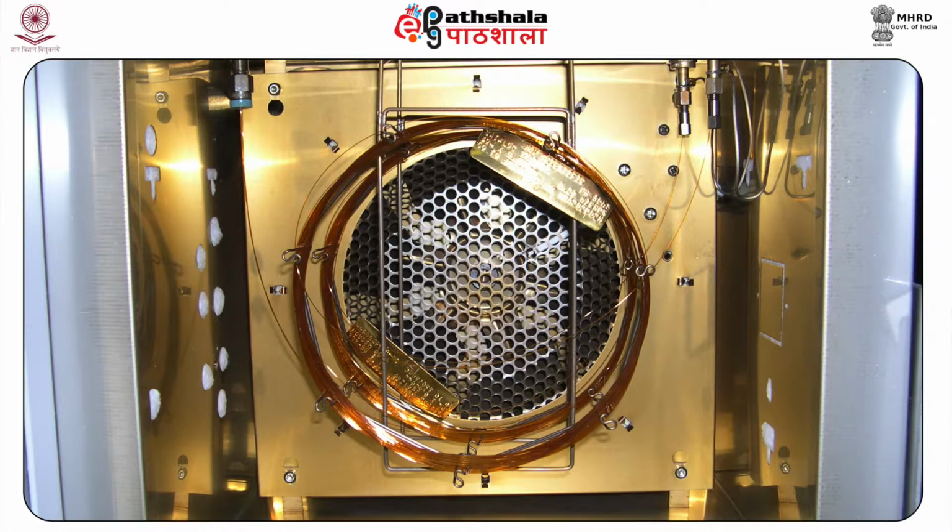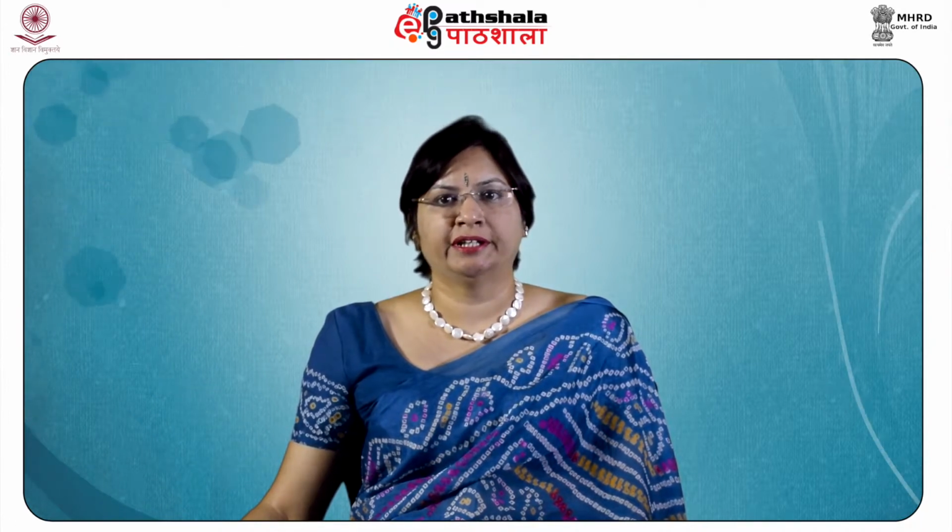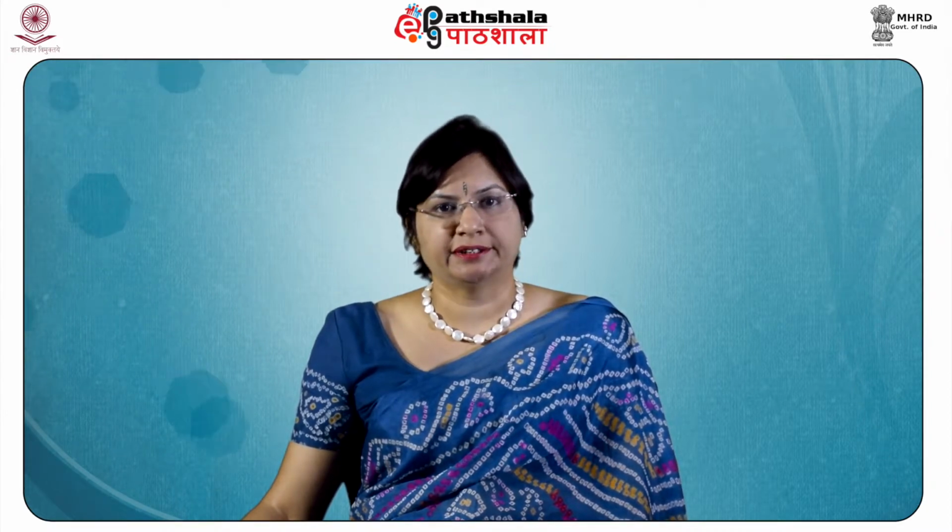So, if it is for petrol or gasoline, it starts at 70 degrees centigrade, it is kept isothermal for 5 minutes and increases at 5 degrees per minute up to 120 degrees centigrade. So, the range is you keep it from 70 to 120 degrees centigrade. Now, if the same process is being done for kerosene, then the temperature starts from 90 degrees centigrade and continues at 10 degrees centigrade per minute up to 220 degrees centigrade. The range is 90 to 220 degrees centigrade and the hold is for 5.5 minutes at 220 degrees centigrade.